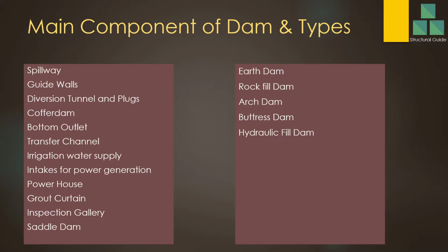Power intakes and power houses may be connected with the dams. Grout curtains: to avoid water seepage below the ground, below the dam body, we construct grout curtains.